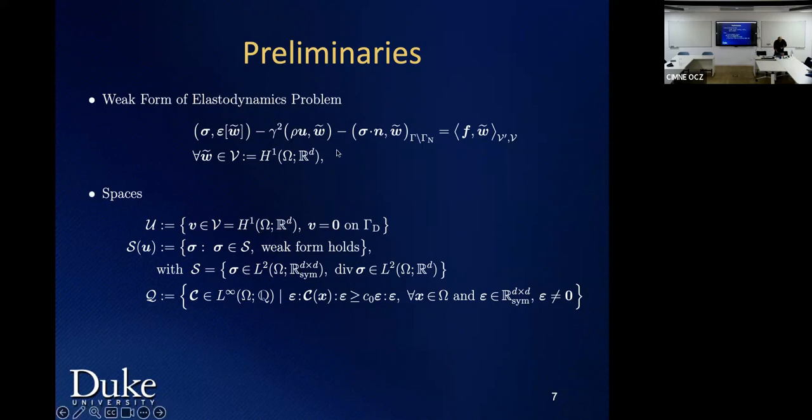All right, weak form, right? So we're going to start with the frequency domain, and I'm going to point you to some terms. Think of elasticity in the frequency domain, right? Elastodynamics, and you have here the first term that will lead to the conventional stiffness matrix and so on. You have what we'll call the mass matrix here, right? And this is going to be frequency for us, the gamma. Then something very important, and then the forcing. Now I'm going to point you to this term here. For us, when we formulate weak forms, usually that term goes away because the test functions vanish at the boundary.